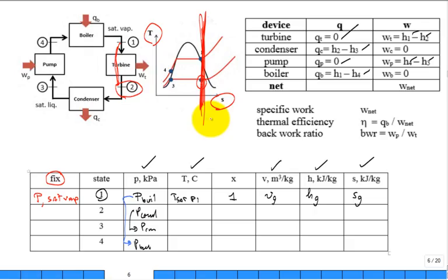So really, one property I can tell right away in this whole list is which property? S2 is equal to S1. This is the same value of entropy. Then I think, if I know the condenser pressure and I'm able to do a second law analysis of the turbine and infer the entropy, the game's up. I've got them all now. I got 2 independent intensive properties. I can get the H. I can get whatever, temperature. True?